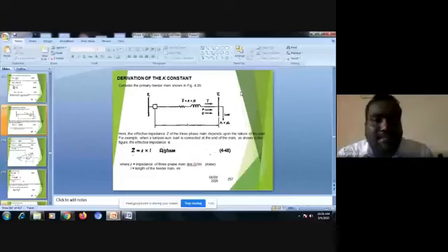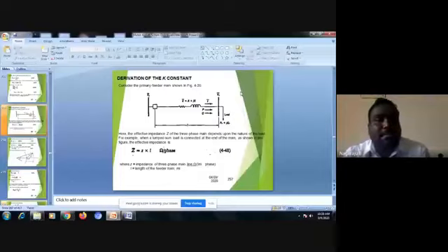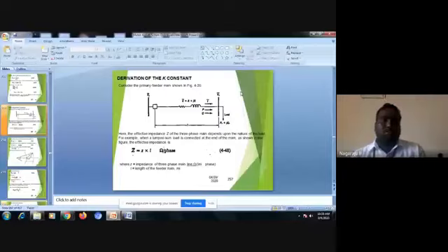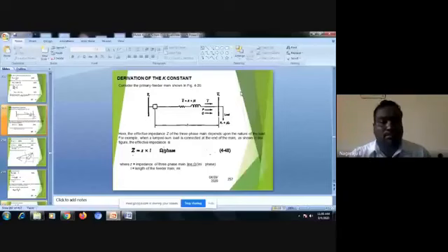So, today I'll discuss the K constant. K is a constant for the voltage drops, K depends on the voltage regulation, and K is a transmission line constant. To derive the K value, I am considering a primary feeder. A primary feeder is nothing but a feeder connection, a conductor from the substation to the main distribution transformer. The conductor has some reactance and some resistance. With respect to the reactance and the resistance, you have some impedance value.